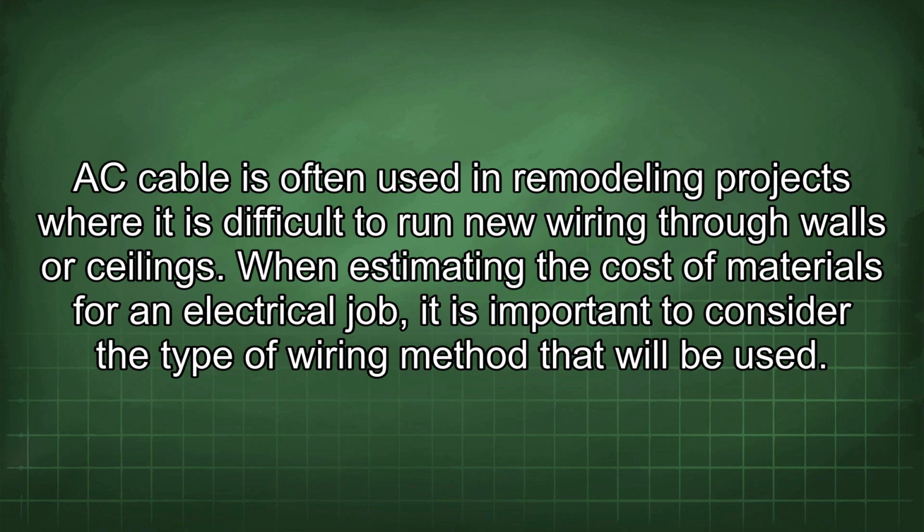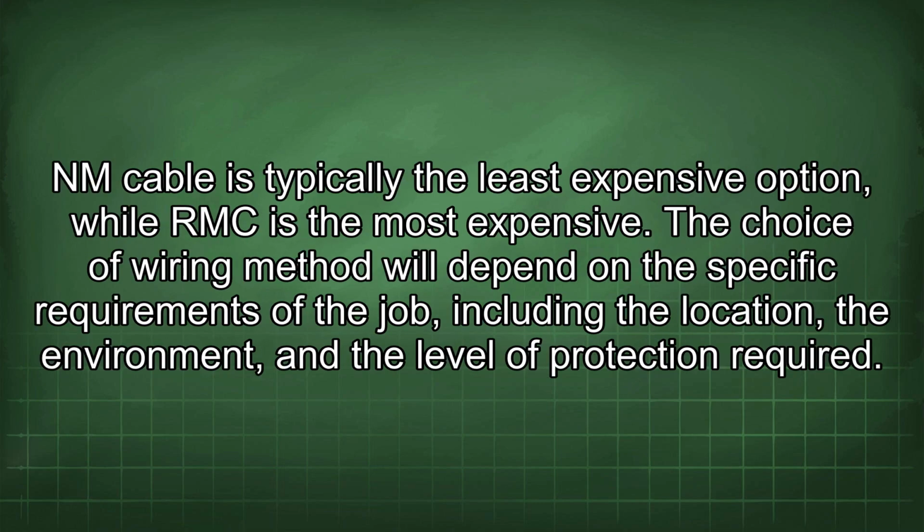When estimating the cost of materials for an electrical job, it is important to consider the type of wiring method that will be used. NM cable is typically the least expensive option, while RMC is the most expensive. The choice of wiring method will depend on the specific requirements of the job, including the location, the environment, and the level of protection required.